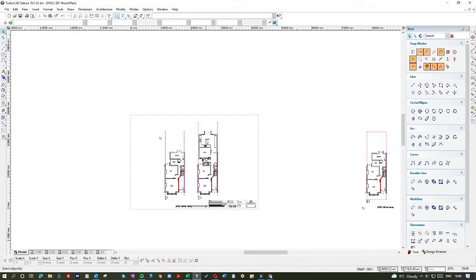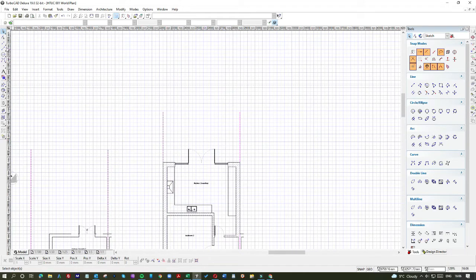Now next thing would be for the patio. So let's do a 3.5 meter patio. So that's tab, and down here 3500. That's to get the depth of the patio. For a patio, again, this simplicity thing always works for me. So patio slabs, different sizes, 600, 450. If I do 600s, they're great, but if I do 450s, it makes the place look a little bit bigger. So I'm going to do 450.